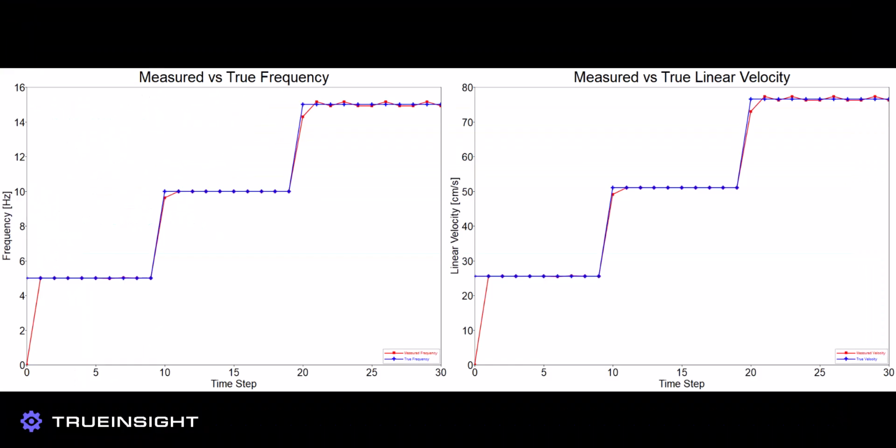We will also verify that our frequency measurement system can handle changes in the input. We can see that as we step through different input frequencies, our estimated output adjusts accordingly, ensuring that we can use this information as feedback in our control loop.